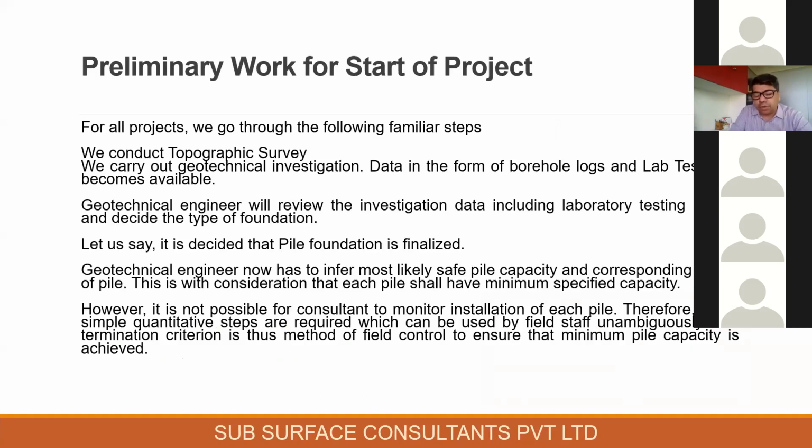All of us know very well that in all our projects we go through the following familiar steps. Initially, when we go to a site, we typically conduct a topographic survey. This is followed by, either normally or in tandem, a geotechnical investigation. In the geotechnical investigation, we generally drill boreholes, collect samples from the ground, take them to the laboratory and conduct lab tests. So bore logs and lab test data become available.